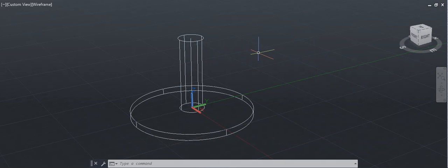One of the things I like to do on this line is divide it into 5 spaces. The divide command will do this for me. So type divide, D-I-V-I-D-E, spell it right, otherwise the computer doesn't make guesses or spell check it for you. If it's a command, you have to spell it correctly. It's more strict than any other program.